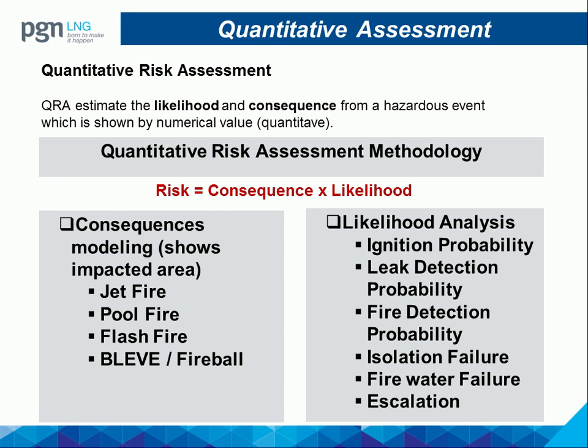And then we also do a likelihood analysis. So how likely there is an ignition, and if there's a leak, whether the leak will be detected by our system, and then the same for fire, and whether there is a failure of our isolation or fire water, in this case our barriers. And the last one would be whether there would be any escalation due to the hazard.